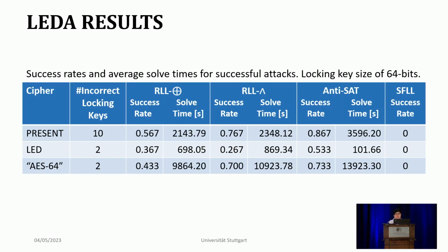For LEDA, we see that the logic locking can make our cryptographic circuits vulnerable to classical algebraic analysis. Like I said earlier, there are no fault injections applied here. We use multiple randomly generated, incorrect logic locking keys to unlock the circuit and apply differential analysis to solve for the secret cryptographic key.